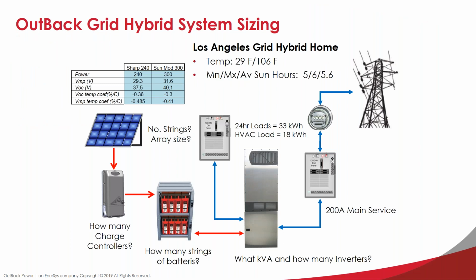Okay, so just to give some context, with a battery-based system, there are a lot of different components or configurations, if you will, as compared to a regular grid tie inverter. With a battery-based inverter, typically we will have a backup load panel. So when we lose power, these loads are the ones that are backed up.